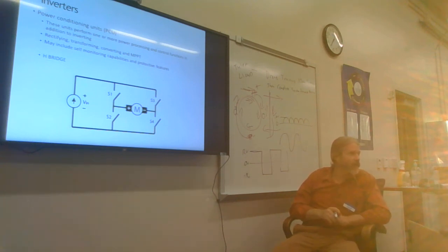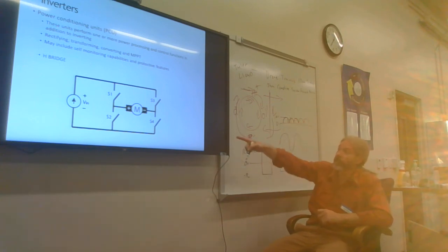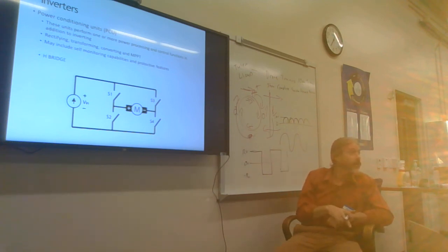So rectifiers that are powered by AC waveforms are actually charging batteries in pulses. Pulse off, pulse off, pulse off. Now, I can actually turn it off from here to here if I wanted to. I could leave those circuits open completely. So I can vary the length of time, the pulse that I'm charging this battery, using this same H-bridge circuit.